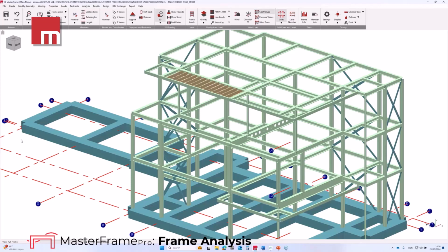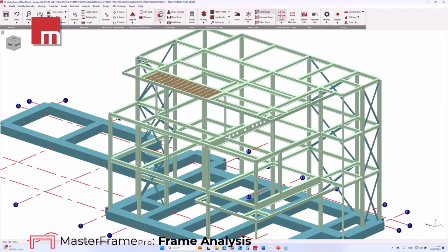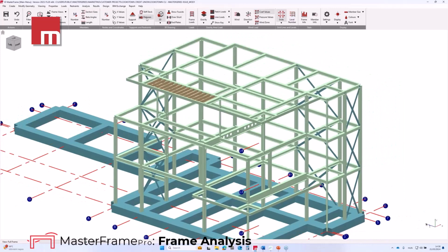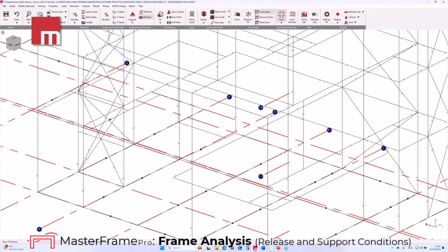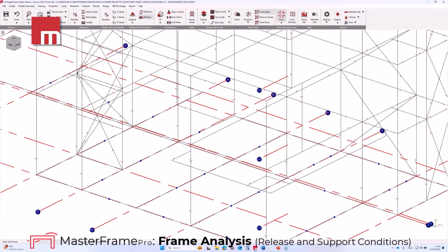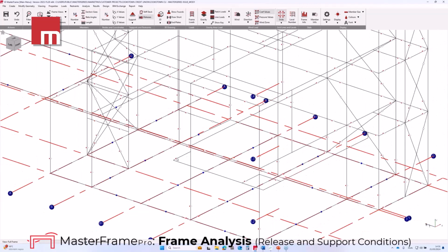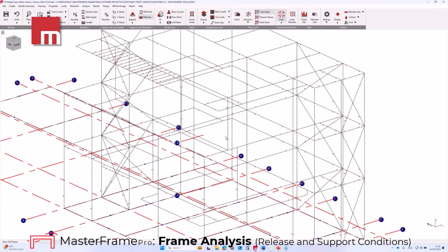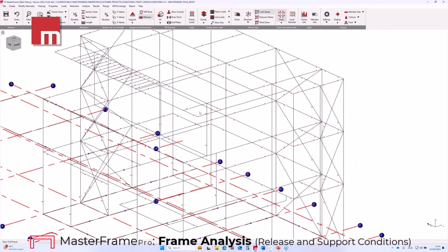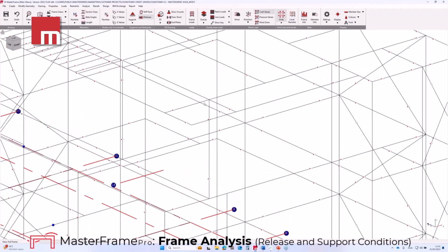them inside the MasterFrame. The building is a simple construction, meaning all the beams are simply supported, except the cantilevers, which support the canopies. The canopy here and here on the roof, and of course the connecting beams are also continuous to avoid torsion in the supporting beam.